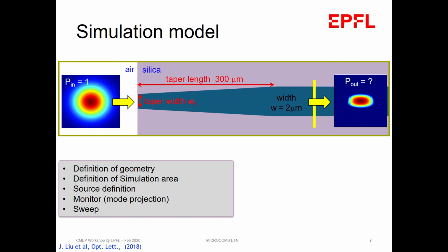to see how the mode is propagating inside this silicon nitride waveguide. We'll try to vary different taper lengths to see the effect of adiabatic conversion, how the mode is converting from the 3 micron Gaussian source to the fundamental mode of the waveguide that we are trying to look at. This is our bus waveguide that is coupled to the microresonator. It's a silicon nitride waveguide covered with oxide. We will follow the same procedure that Jung-Q already told you, where we define the geometry: our waveguide consists of silicon nitride, and our cladding consists of silicon oxide.